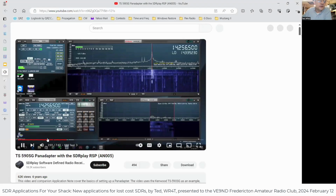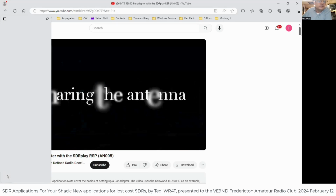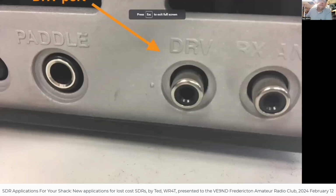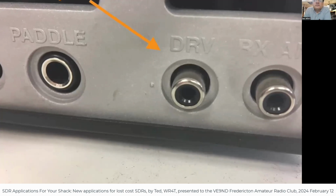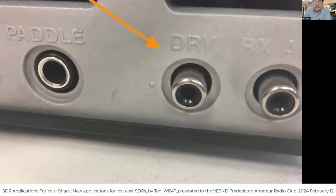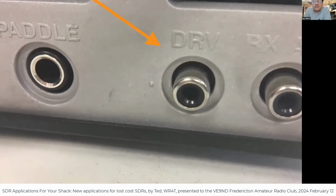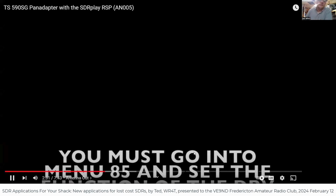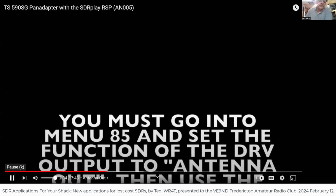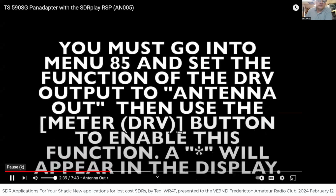By a screen with the range from 14 to 14.35 megahertz. There are several ways to connect an antenna in a pan adapter configuration, but one nice feature that the 590 SG offers is the DRV output, which can be configured to be an antenna out, effectively providing a nice clean signal to the RSP without fear of it being overloaded when you press the transmit key. The DRV output can be used in two ways, either to drive an external amplifier or in our case as an antenna out jack. So you will have to go into the menu system.